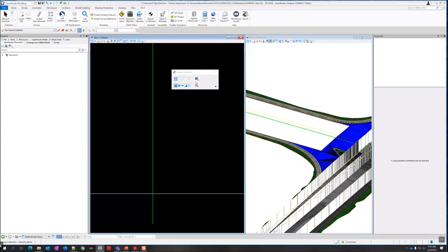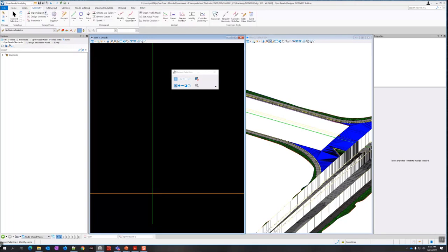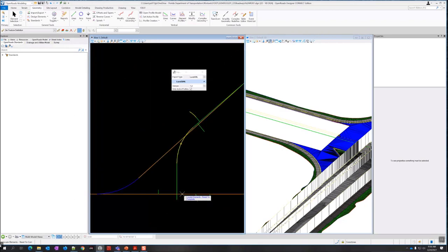So let's go ahead and do the same process for the other center line. So this baseline, 98. Let's just go back here to geometry, import, export. And this time, since the last tool I used was export, I can just click the button. It's going to go straight back to the same tool. Export geometry. Type is LandXML, and then select the baseline of US 98, which is the orange line down here. Reset to complete.